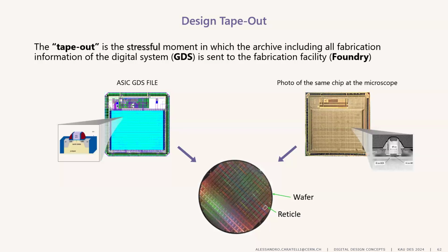Then on the FPGA, we run some testing routines, like sending and receiving test vectors. Also, for testing the fabrication of the chip, to see if the chip works or we need to exclude it, we use an approach called scan chain. Scan chain means that all the flip-flops of the chip are connected in a long chain, not when the chip is functional, but only for testing purposes. So you can shift in a test vector, give a pulse of clock, and then shift it out. This allows you to test basically everything on the chip in a few hundred milliseconds. Generally, we do this from an FPGA.